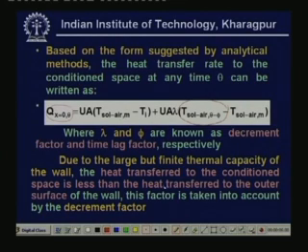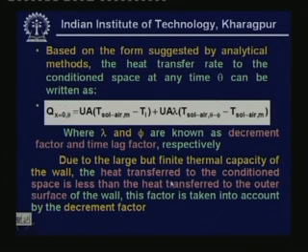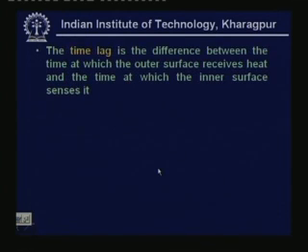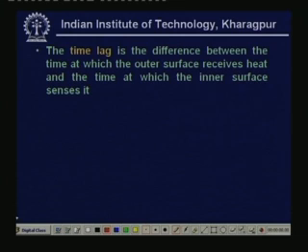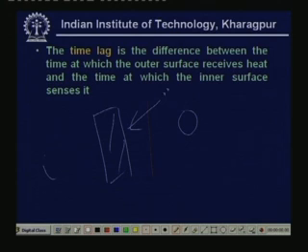Similarly, you have what is known as the time lag factor. And what is the time lag factor? The time lag is the difference between the time at which the outer surface receives heat and the time at which the inner surface senses it. So let me give an example. Let us say that you have a wall here. Let us say that this is a wall, and this is the outdoor and this is the indoor.